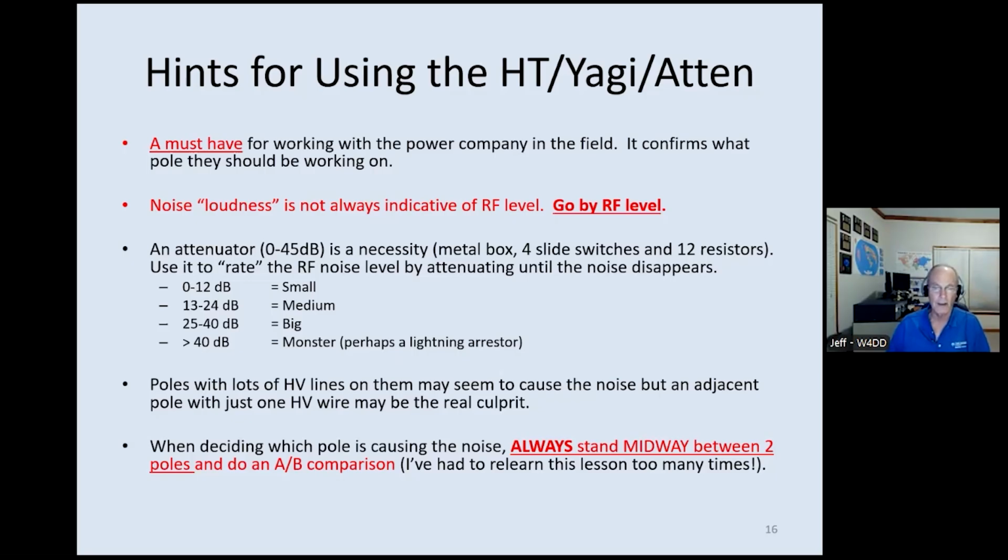With a spectrum analyzer, you may have a little more problem doing that. Now, for switching mode power supplies, a spectrum analyzer could be a very useful thing because you're looking for a signature there. And sometimes you want to see, am I chasing the right thing? So there are cases where it comes in really handy.